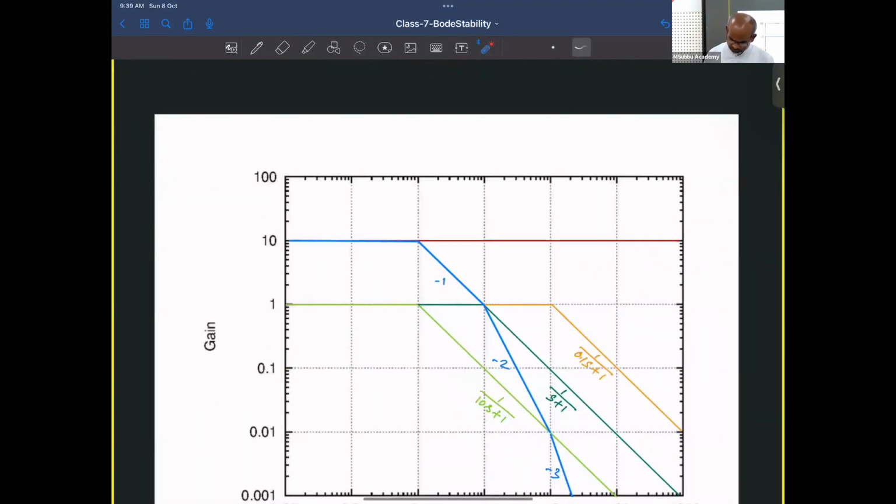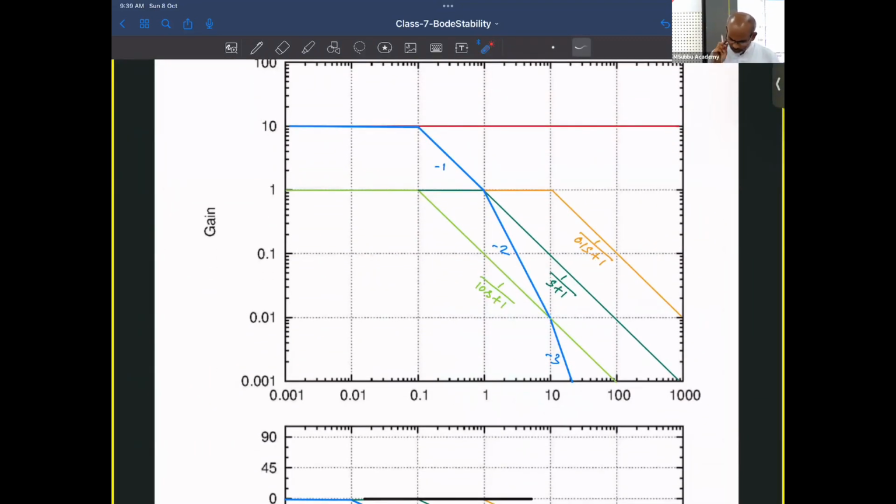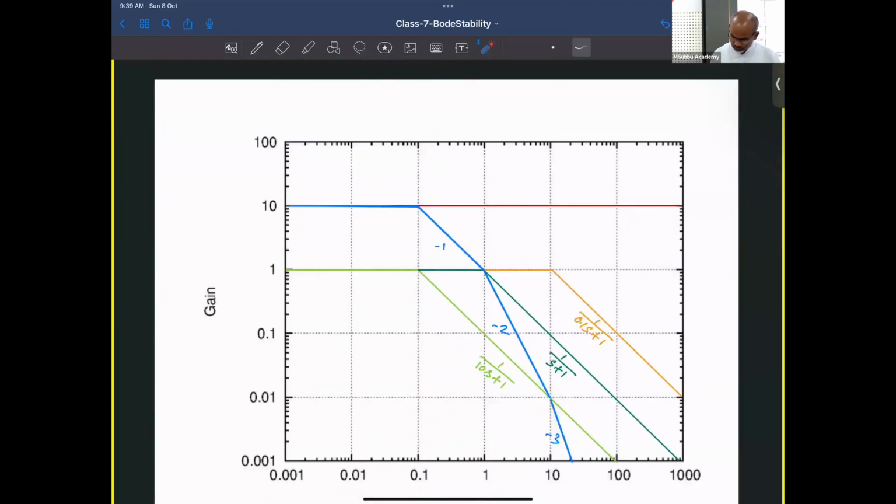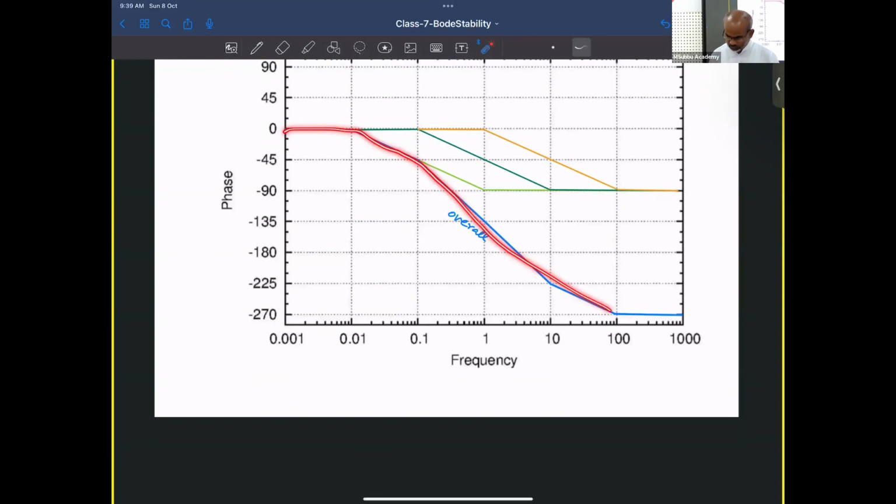And in constructing this gain plot, of course, this is for the first system, and next is for the second system, and this is for the third system. All are in series, and already there is a gain of 10. So starting from the highest gain, make this overall line till a point of 0.1, where we have the slope of 0. After that, slopes are different. So for that range, you make these lines. These lines you can easily do because these are all having 1 and 1 units. By that way, we have this total amplitude ratio, and earlier we also had this phase angle plot.